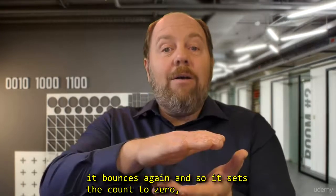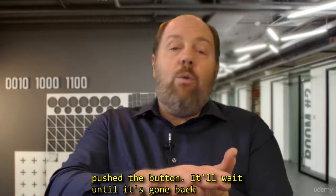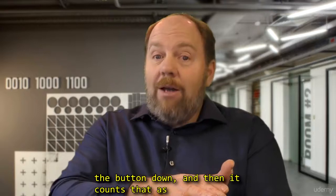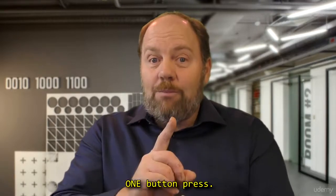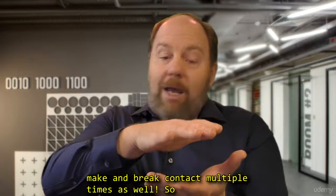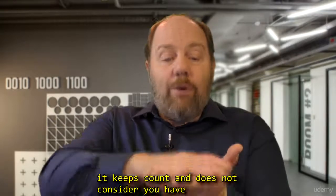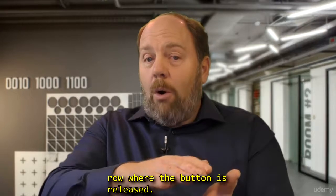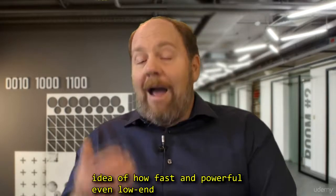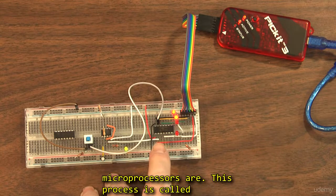But it bounces again, and so sets the count to 0, and starts counting again when it detects you've pushed the button. Now it'll wait until it's gone back for, say, 50 cycles in a row, where you were holding the button down. And then it counts that as 1 button press. Then it waits for you to release the button. But as you're releasing the button, the contacts can make and break multiple times as well. So it keeps count and does not consider you have released the button until it counts 50 cycles in a row where the button is released. Now, it may seem ridiculous, but this just gives you an idea of how fast and powerful even low-end microprocessors are. This process is called debouncing.